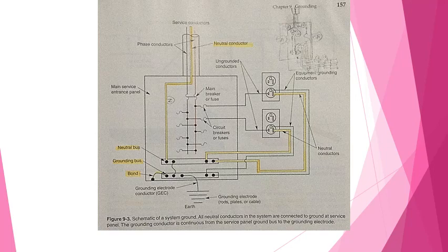The neutral or line conductor selected to be grounded is connected to a grounding electrode. This may be a driven rod, a driven ground rod that reaches at least 8 feet deep into the ground for contact with moist earth. A metallic water piping system of 10 feet or more in length. A buried ground plate.